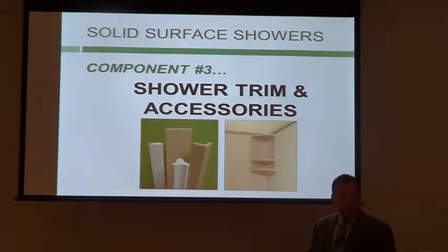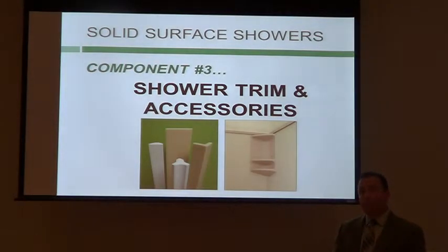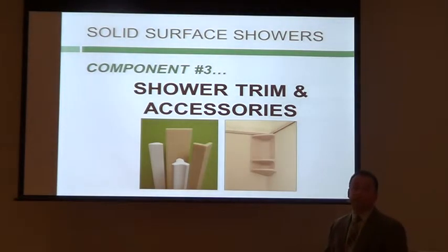So if you add inside corner trim, it'll eliminate the concern for any moisture getting into the cavity of the wall, and believe it or not, it speeds up installation. So it can actually lower the installed cost.